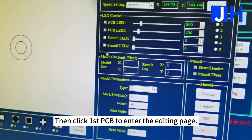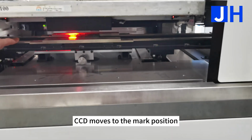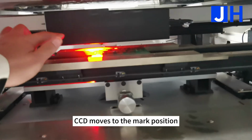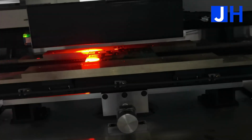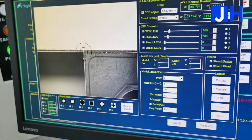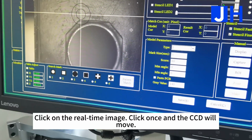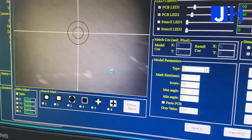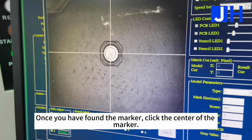Then click Illustrate PCB to enter the editing page. CCD moves to the mark position. Move to the upper left side of the PCB. Then we go to find the mark point here. Click on the real-time image, click once and the CCD will move. Once you have found the marker, click the center of the marker.